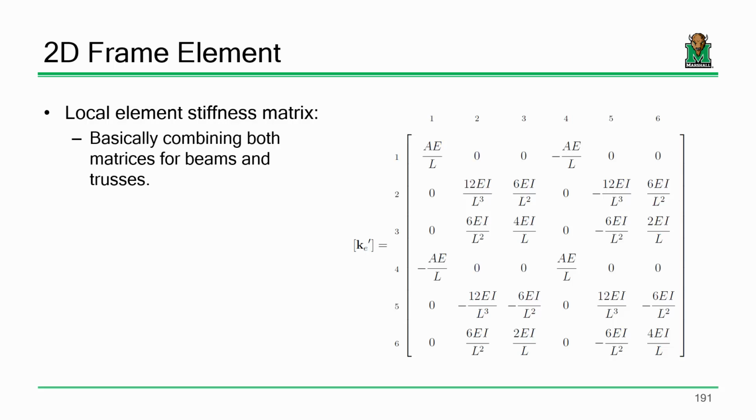I'll say this about shear deformations. Shear deformations become a more critical phenomenon when you have a beam that is really, really deep. Okay? If you have a really, really deep beam, then you need to consider shear deformations. And in those scenarios, you might populate some of these terms with zeros. At the very least, some of these flexural terms will have shear deformation added to them.